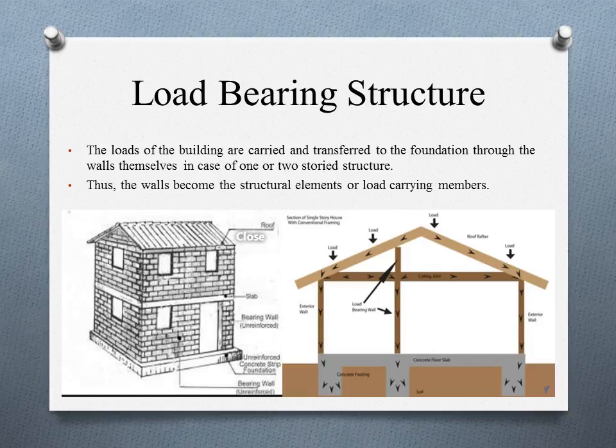It has thick brick wall, as the construction is made up of brick, so it is a thick brick wall. Thicker walls give more weather resistance and noise protection. It is good and cheap for less than 2-floor construction because the bricks are cheap. Disadvantages: it loses carpet area due to more thickness of wall. Labor work is increased and material like brick is also required in huge quantity.